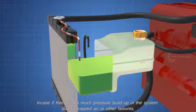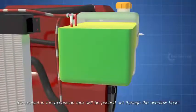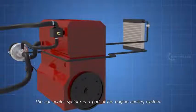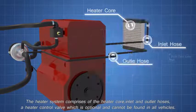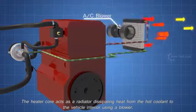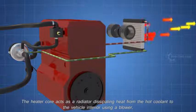In case there is too much pressure buildup in the system, due to trapped air or other failures, the coolant in the expansion tank will be pushed out through the overflow hose. The car heater system is a part of the engine cooling system. The heater system comprises the heater core, inlet and outlet hoses, and a heater control valve, which is optional and cannot be found in all vehicles. The heater core acts as a radiator, dissipating heat from the hot coolant to the vehicle interior, using a blower.